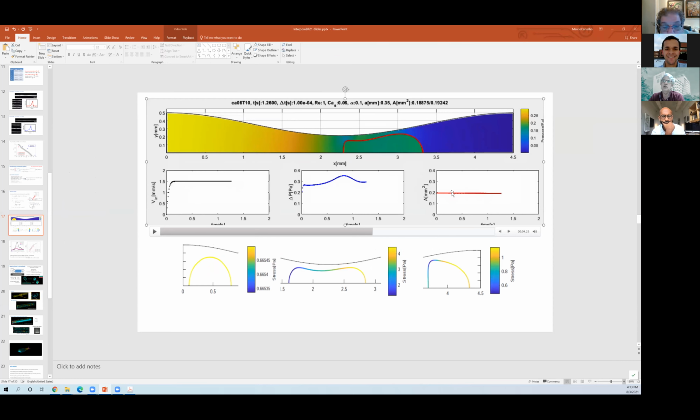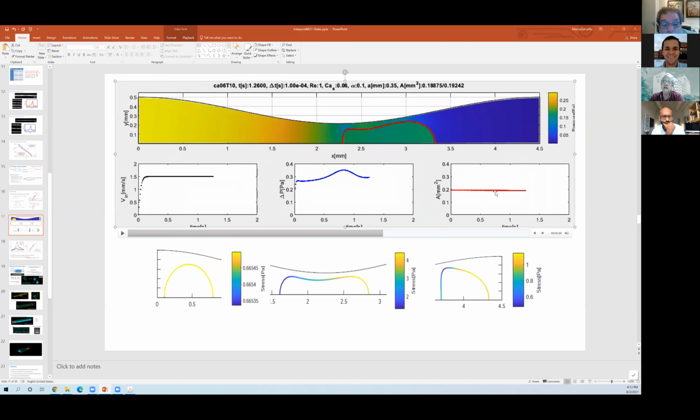So this is tracking the area inside the capsule, because I'm compacting this one-dimensional mesh through the fixed two-dimensional mesh for the flow. One of the limitations for such a model is that you may have a net flow through that boundary, because nowhere do I impose that n dot v has to be equal to the velocity there. So that's why we need to track how much mass is lost.